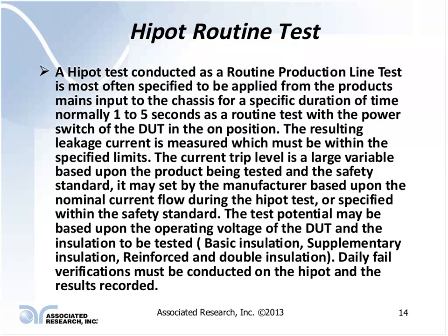insulation that basically may be the basic insulation and some type of supplementary insulation between what are normally current carrying conductors and what is not meant to be a current carrying conductor. And when that occurs, normally the test potential that is applied to test a double insulated product is twice the voltage of the potential that is applied for a Class 1 product.